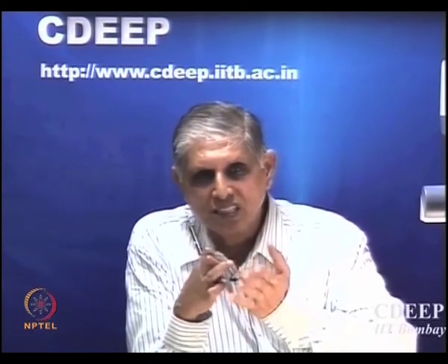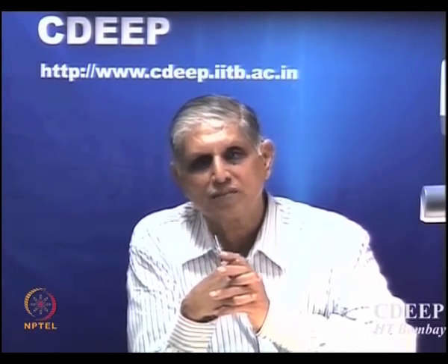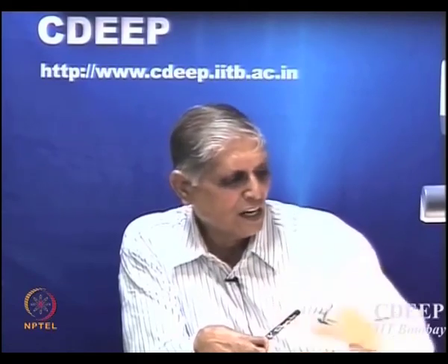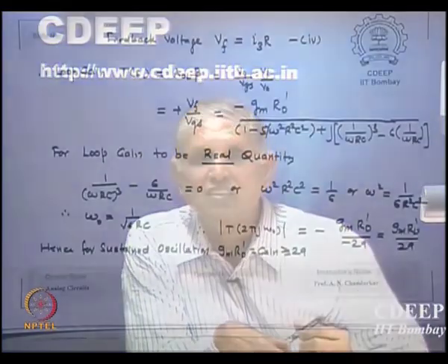By choice of bias current, the DC, or if I am on an integrated circuit, I can also choose W by L, the size of the transistors. In this specific case, we say only bias current can. So adjust your DC network to get whatever Gm you want. Loads also you can adjust because Rd dash will decide the gain, so you can adjust that value as long as this value meets 29.